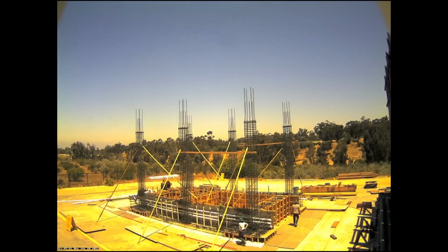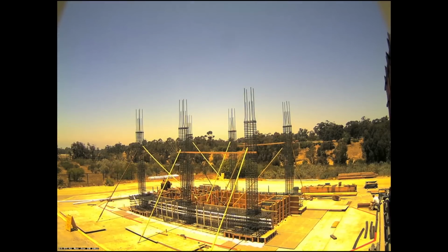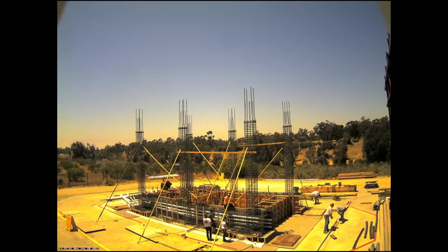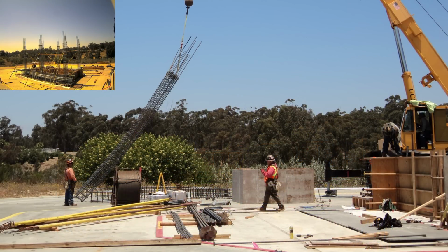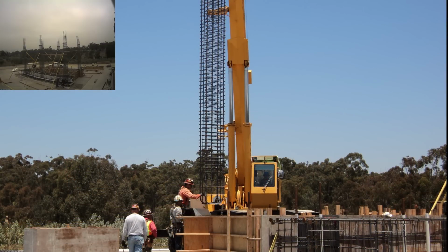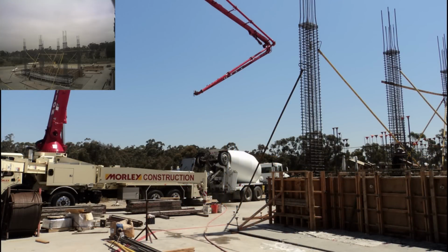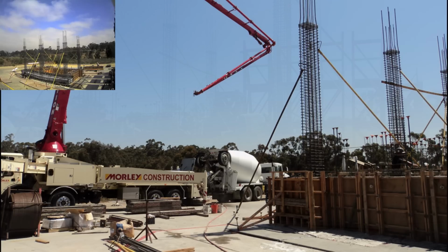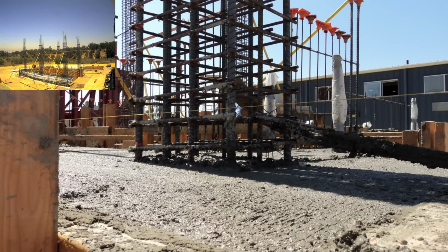In order to ensure that the foundation and the main building structure are continuous, the reinforcing steel required for columns and walls at the lower levels of the superstructure must be built integral with the foundation. In this project, during placement of the foundation reinforcing cages, the reinforcing cages for the columns were placed and extended well into the upper levels of the building. This enables the starter rebar for the columns and walls to already be in place when the footing concrete is poured. The columns are detailed with a prefabricated welded tie tightly spaced up its height, encapsulating the vertical bars, and these are also in place when the foundation is poured to provide stability to the column reinforcing.